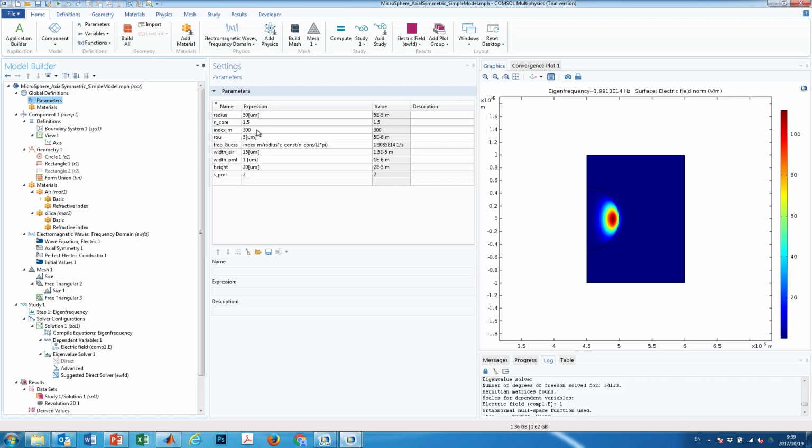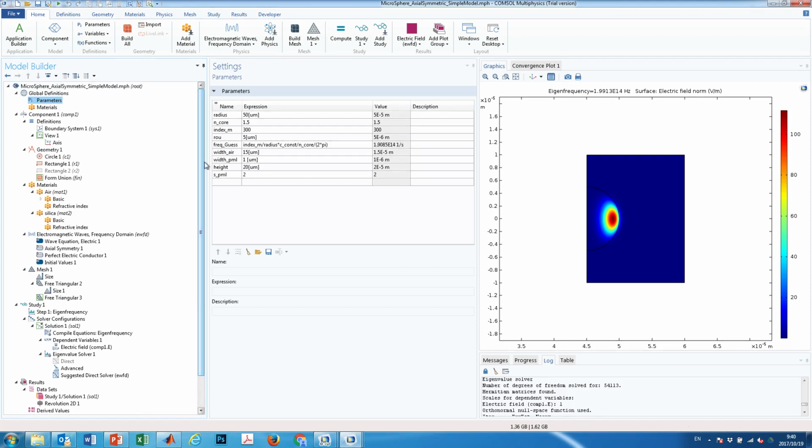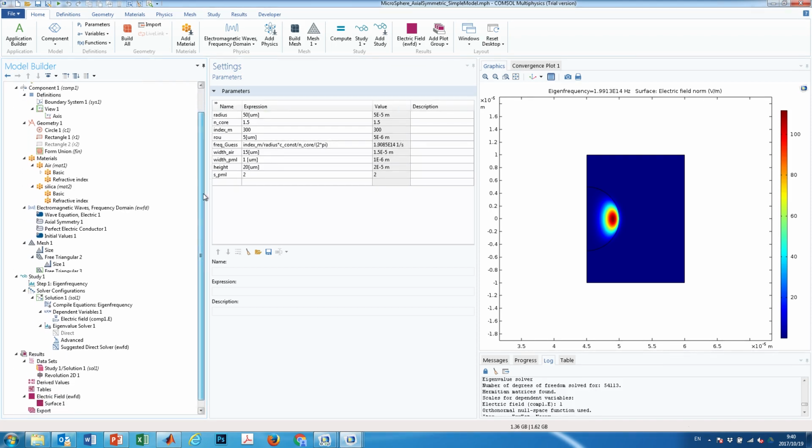There are physical reasons why we choose these values and why the simulation becomes more comfortable eventually. You can already define the mode. This is because the more bending you set, the higher the potential of those leakage modes. So that's why the system will find those fake modes instead of the real modes. If you just put the radius a bit longer, then things can be solved.